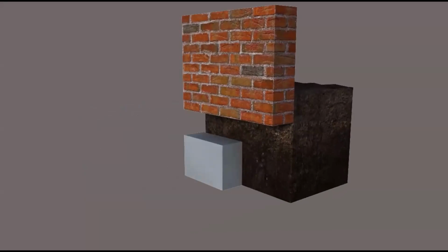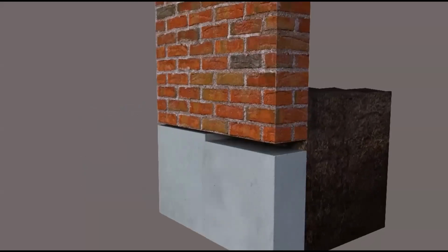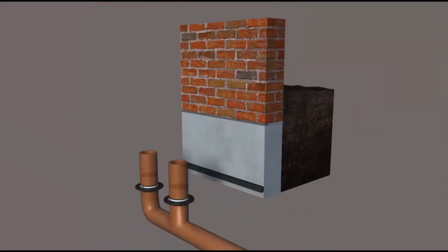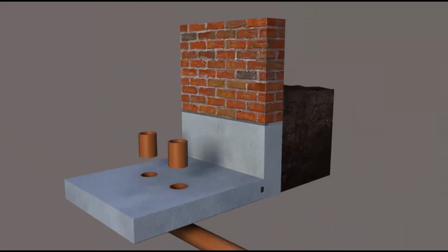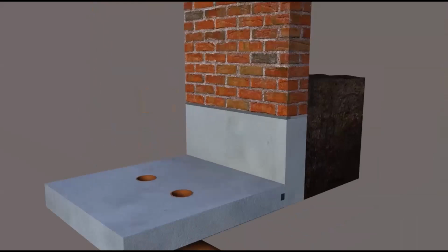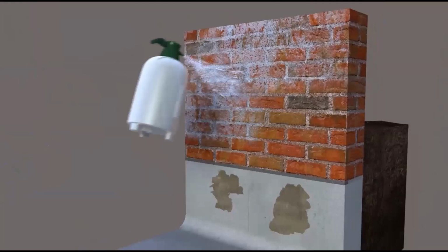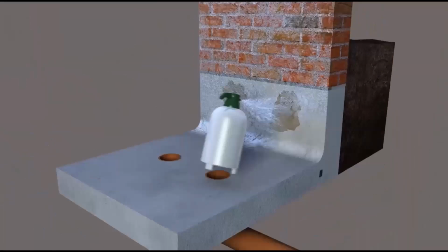Underpinning, a very quick illustration now with no sound on it, so hopefully you can hear me. Dry pack joint, we have a repair mortar plus pointing. That's an expanding repair mortar. We've got a water bar, got a slab going in, got a fillet of repair mortar there. We've got defects in the underpinning. We address those using leak sealing products to lock it down.